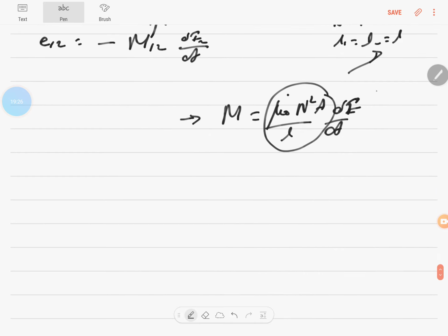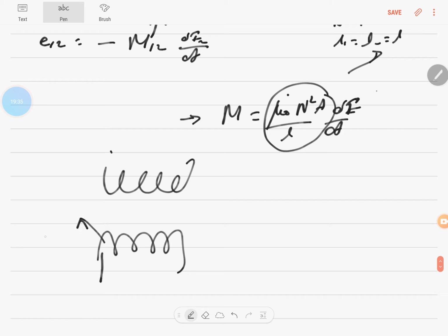And you should know the relationship between self-inductance and mutual inductance. In mutual inductance, some amount of flux can get leaked into the outer atmosphere. All the flux change is not going to produce an EMF in the other coil. Some amount of flux will get leaked. There will be flux loss. Supposing you take the self-inductance of this, which is L1, and the self-inductance of this, which is L2. Individually L1 and L2 are the self-inductances.